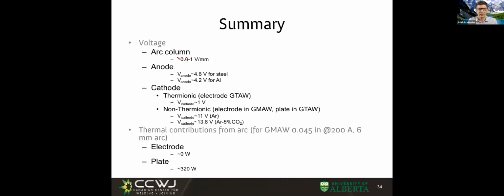And by the way, I presented this for people of industry doing R&D to design machines, and they said this is dead on the money. So perfect. So good. And 1 volt per millimeter for TIG, in both with argon shielding gas. Helium gives you higher voltages, but I don't know how much higher yet. We have everything to measure this in our lab. Our lab is closed now, but if you're ever curious and you'd like to make better numbers, we can do them in our lab.